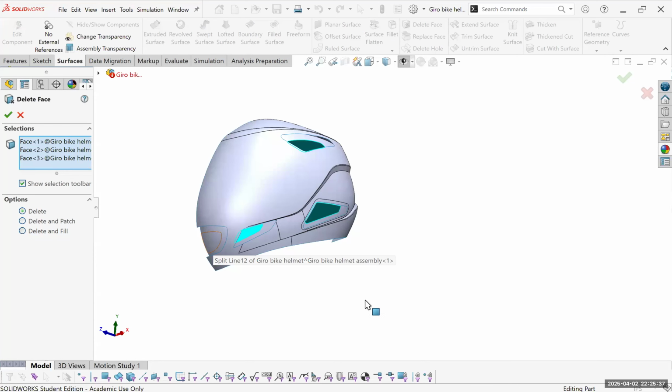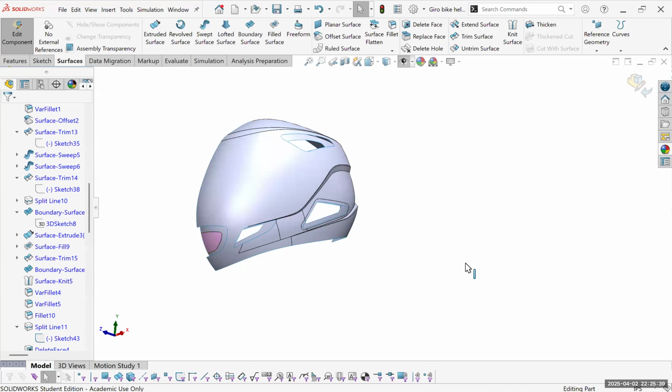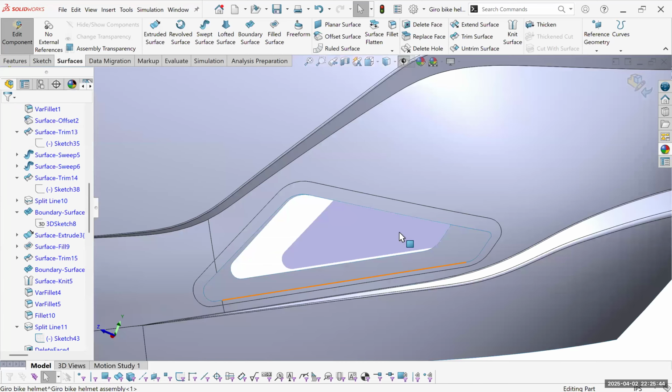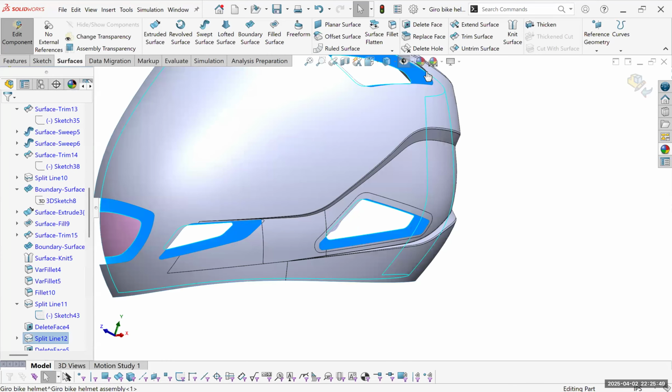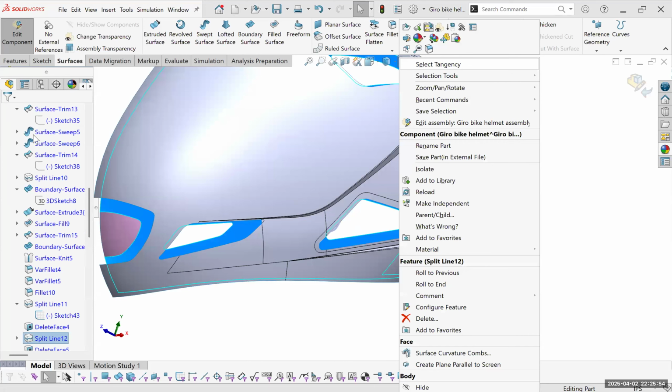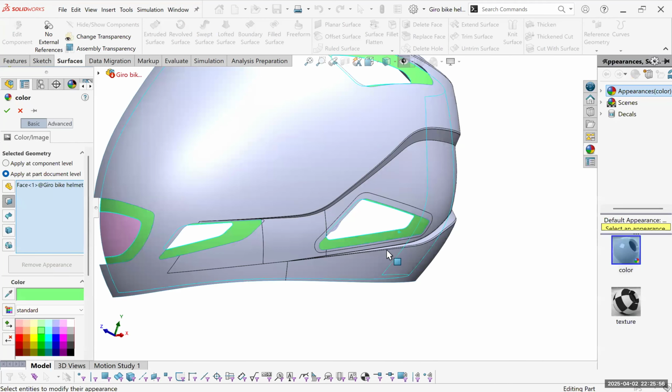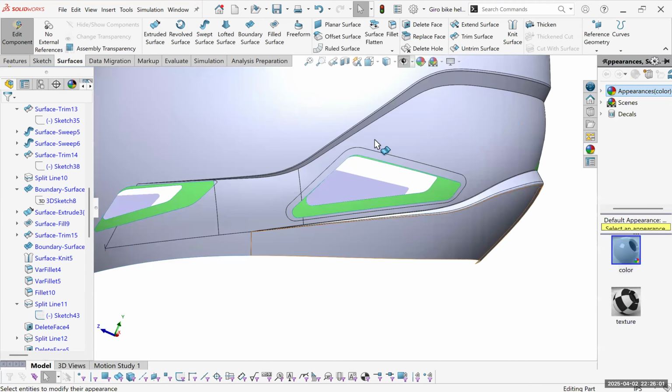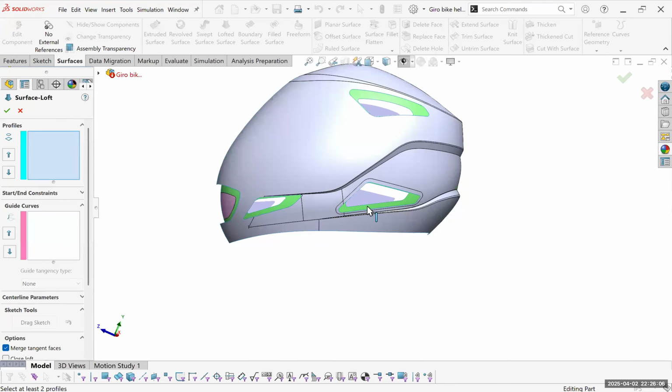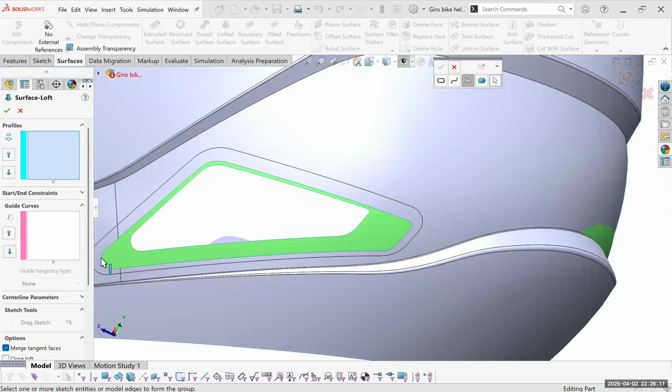All right. Now this is actually pretty fun. We're gonna go ahead and loft edge to edge. So one more time, I want to color this surface so it's easier to see. Gray on gray would be really hard. So now I'll just make it green. Okay, let's go ahead on our loft. If we have nice sketches, this should loft very cleanly. Selection manager. And remember where you start selecting from.